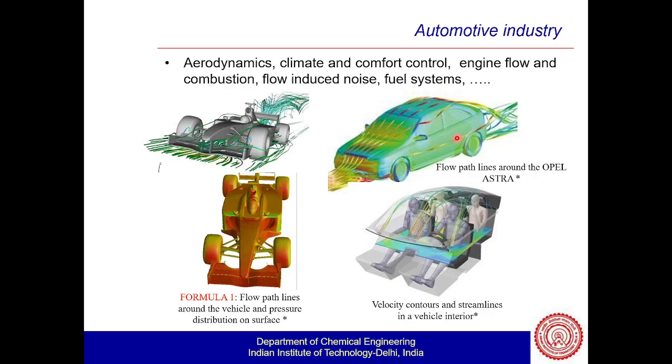We are going to solve these using different schemes like the QUICK scheme, the upwind scheme, and central difference. We are going to talk about transportiveness and conservativeness.